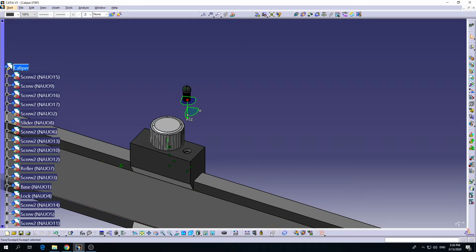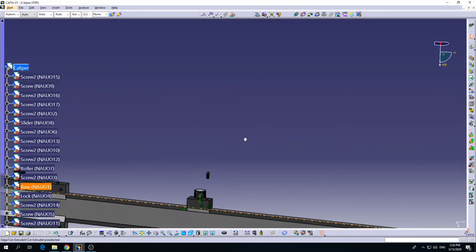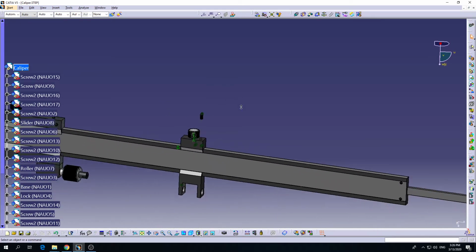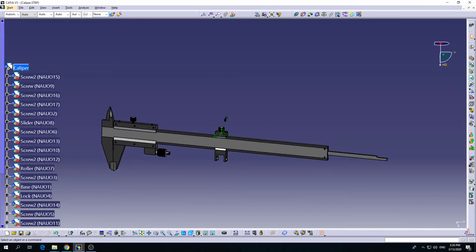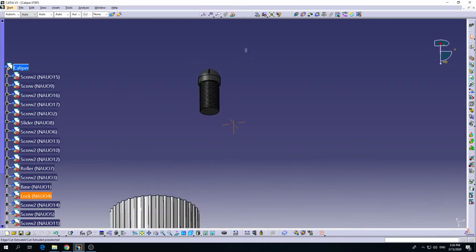And now I will press update. Now I can select the red dot within the compass, and I will left click the compass anywhere in the viewport, but not on a part. So over here on the background, I will left click it, and it will automatically reposition in this section. And now I will define the constraint for this one. I see that the rotation pivot is not optimal now, so I will reframe all, and now it will be centered within the middle again.